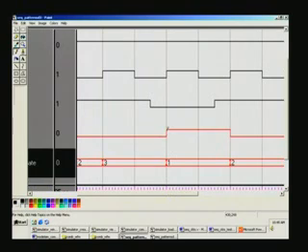So you can see once again it's taking place only, all outputs take place only at the following clock edge, right? Being a synchronous machine. If it is a Boolean expression, then it would have taken immediate effect, right? So being a sequential thing, it will always take place only at the positive edge of the clock. So the state itself is changing at this positive edge.